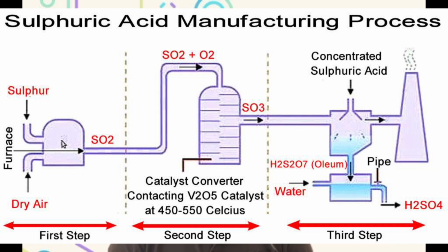After passing through the third catalyst bed, a stream of hot sulfuric acid flows down the absorber, where it meets the rising gas. Acid concentration rises to around 99% as a result of the reaction between sulfur trioxide and water. SO3 plus H2O equals H2SO4.